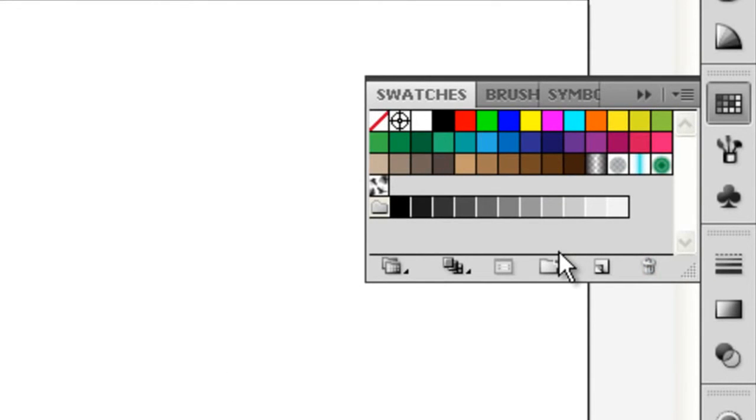If you use the palette for other items such as graphic design and stuff like that, this is not necessary, and I'm not going to go through and actually delete every one of them. And I also recommend keeping the grayscale. They're all part of the shade of gray or black, and you'd use the black power setting, but the grayscales will give you different halftone patterns, so leave those as well.